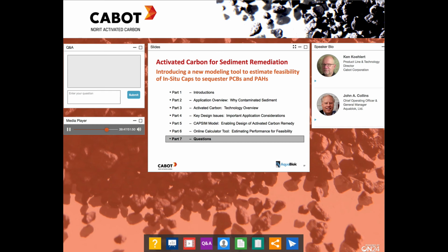Sorry about that. This question here from Summer: is activated carbon mixed with sand in an application for PCB remediation? Activated carbon can be mixed with sand. If you're going to mix activated carbon with sand, it can be mixed in a number of ways. It can be mixed in the form of an Aquagate plus PAH product. That's the way that we've promoted and we've done it because it helps the activated carbon stay mixed with the sand while being placed through the water. However, there have been applications of granular activated carbon mixed with sand, and those have been successfully placed as well.